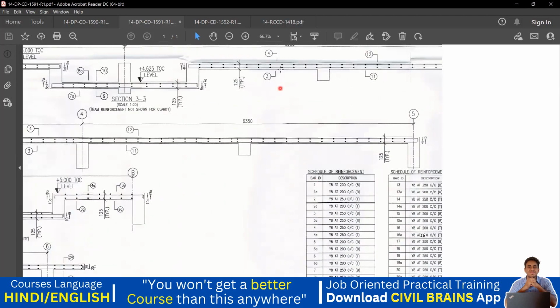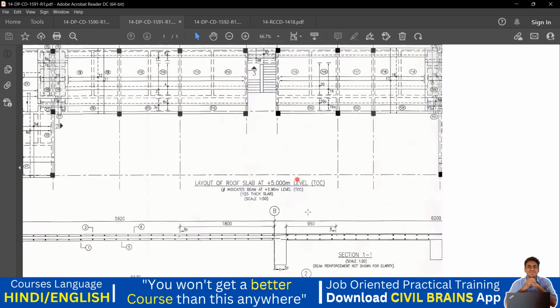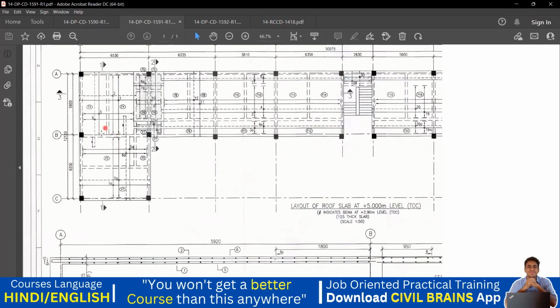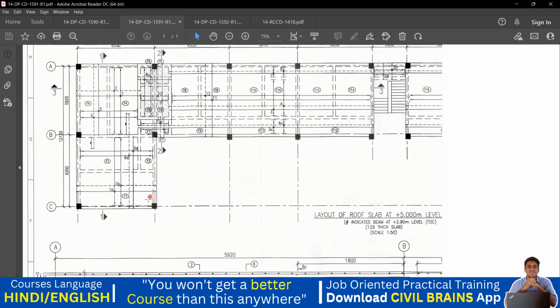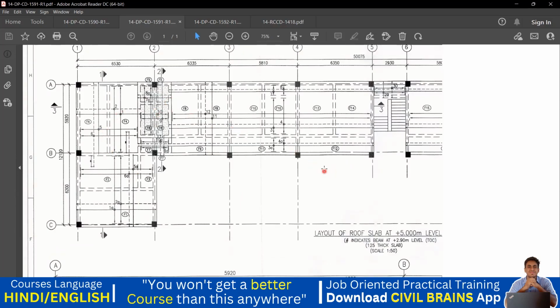Again, if I want to understand what is the reinforcement for the 4 here, come here, you can see here 8 diameter bar at 250 center to center spacing, T is written. So it's shown in top, no? By default, it has come as T. Now again, I'll verify the T, whether it is given dotted in the plan or not. So I'll go back to the plan and we'll see the number 4. I'll search for number 4 here. So the number 4 should be somewhere here. So it is 1, 5, 6, 1, 2. Yeah, not able to find number 4 here.